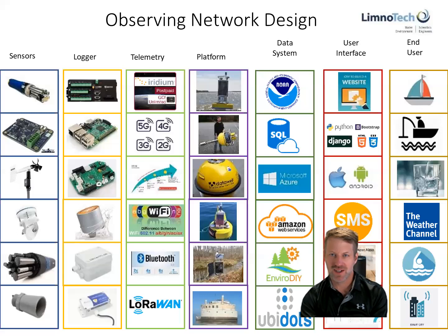When we think about how we set up an observing system for wetlands, I generally approach it with these components that you see on this slide. So if you imagine on the far left-hand side of this slide is our wetland system. So this is our environmental phenomenon. What are we trying to monitor, understand? And usually with sensors, we start with the simpler hydrology-based ones, how much water is moving. We can also get into water quality, how turbid is the water, how green is the water. There's a few sensors. We can look at soil conditions.